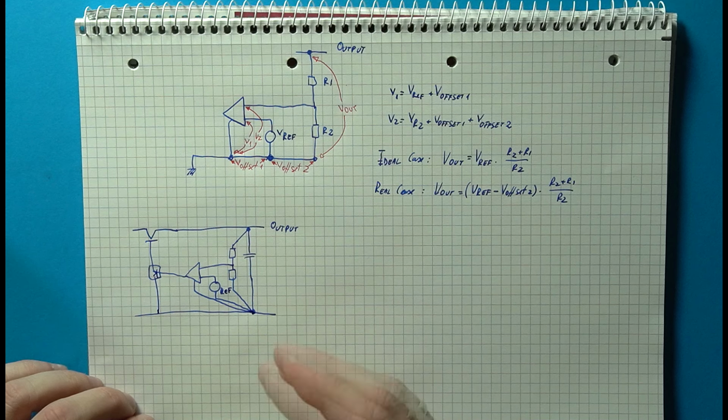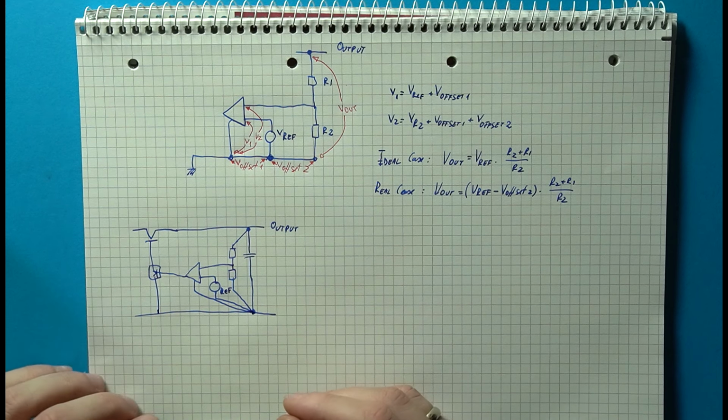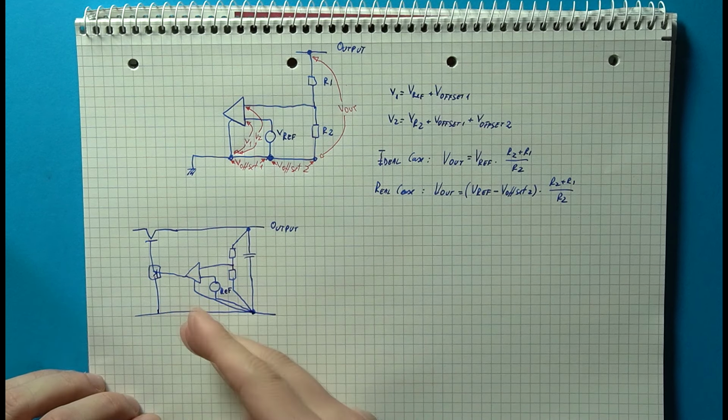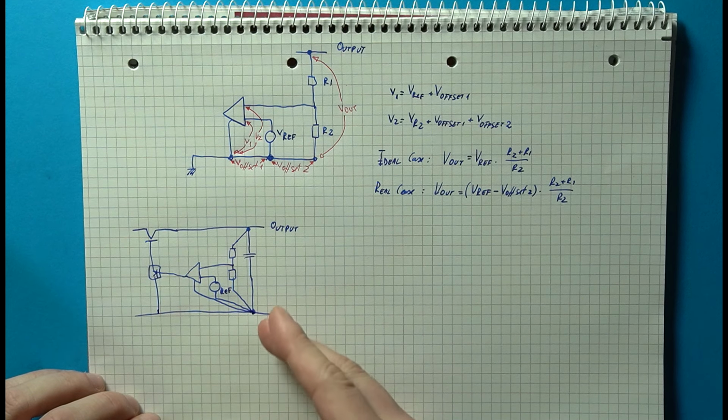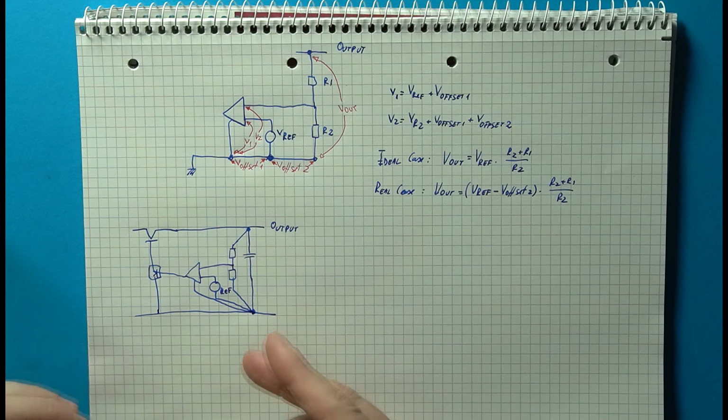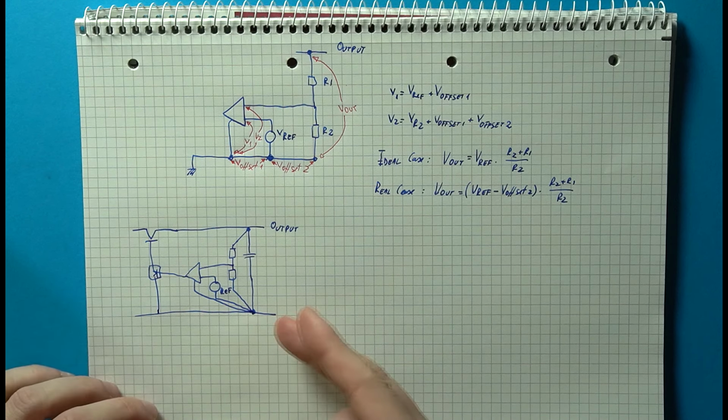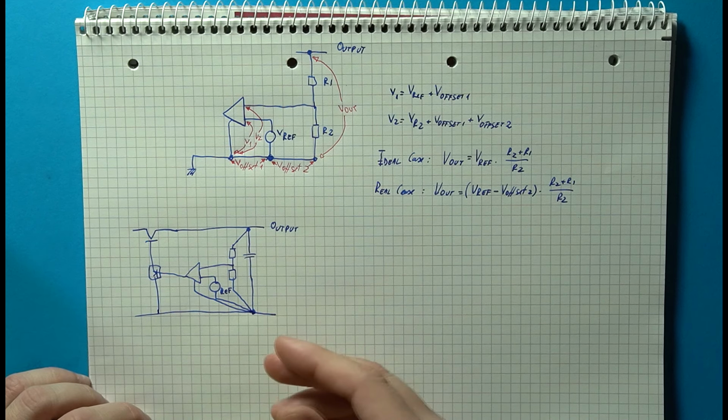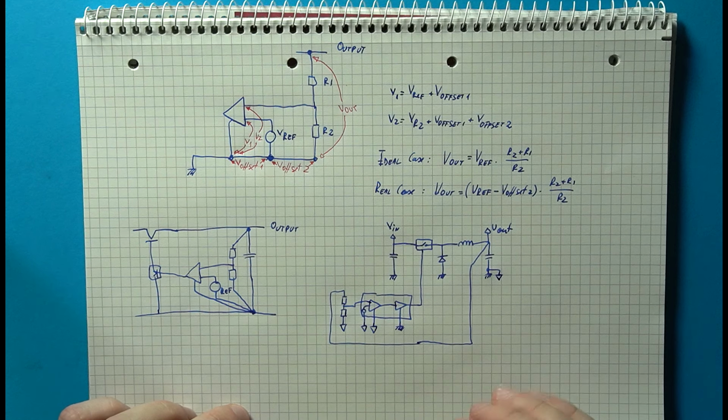One workaround found in older schematics, or when discrete implementations are used, is to have all of the sensitive circuitry connected into a single ground point at the output of the power supply. So to have a ground star point which will not allow any sort of voltage differences to occur between the various important circuit bits. In more modern times, this problem has become even more stringent, specifically in things like switching converters, where you can have very high currents with very fast transitions because of the switching circuitry. And this can cause large potential differences.